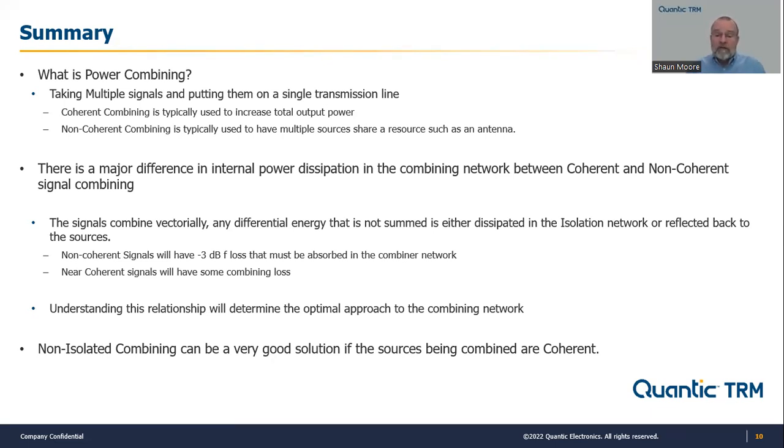I think it's really interesting, as you look at what you have for matches of amplifiers, if you're thinking about making sure your overall efficiency is good without wasting a lot of energy, if you can get your amplifiers matched pretty well, very often you can actually benefit from a non-isolated combining solution. Very often it can be the best scenario for you. It's always a good trade-off, and it's always good having the conversation to see which method of power combining best suits your needs.